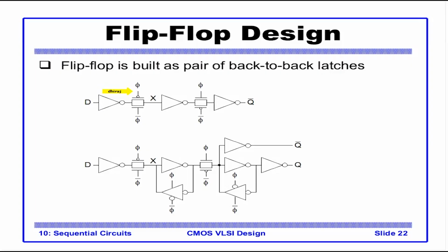So whenever the clock is low, there is no direct connection from D to Q. This is in fact the flip flop functionality. When the clock is 1, X to Q is connected, and D to X is not connected. So whenever the clock is either active low or active high, that is the stable case, there is no direct path from D to Q. Now what happens when the clock goes from 0 to 1?